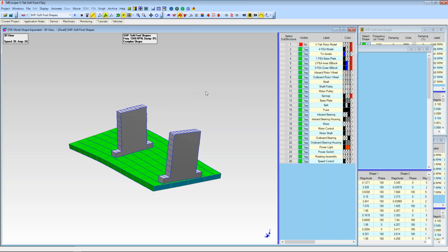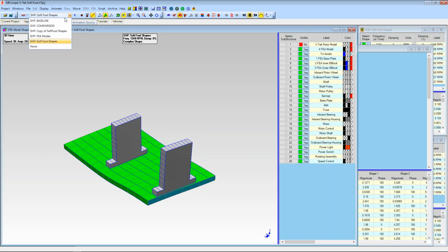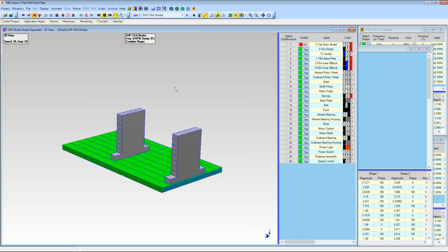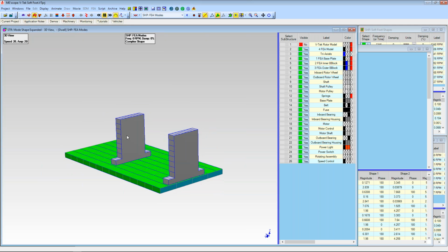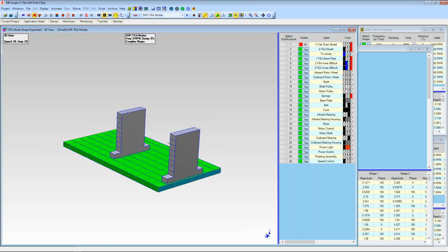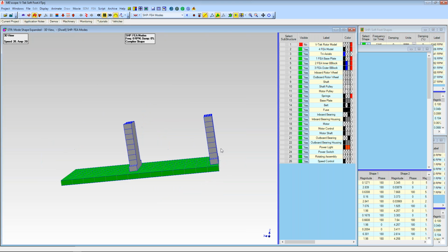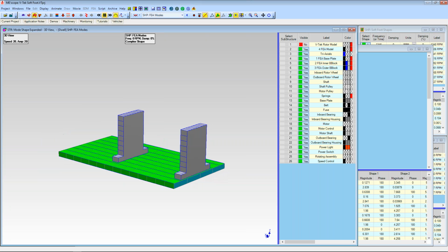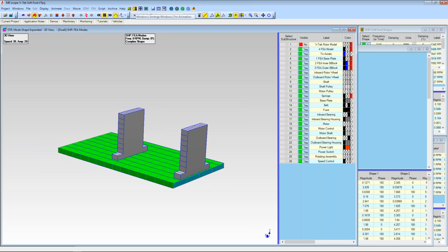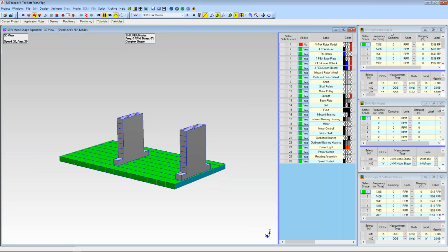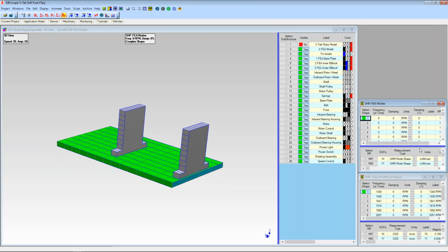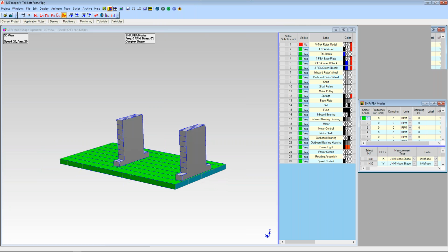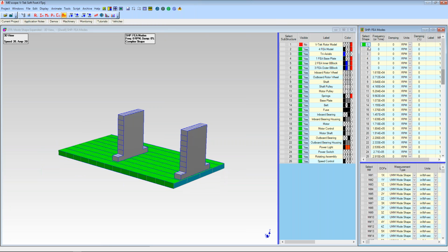These are the mode shapes of the bearing block and base plate. And as I said, we used our FEA capability to get the modes of one bearing block, copy and pasted them to the other one, and mounted the bearing blocks to the base plate with very stiff springs. Let me get these up here. Put those down, and we'll hit the arrange for animation again. So here are the mode shapes.